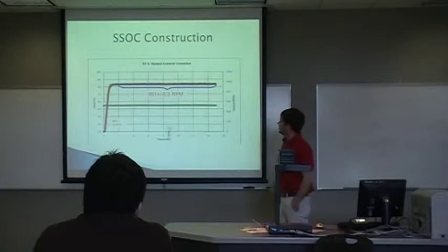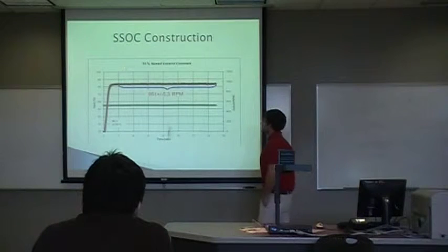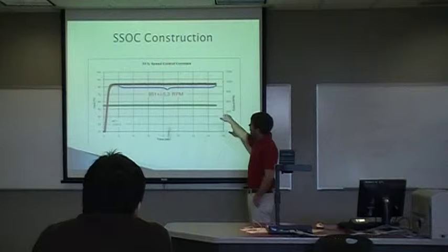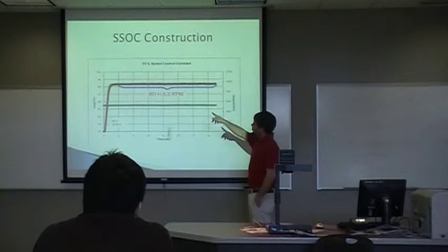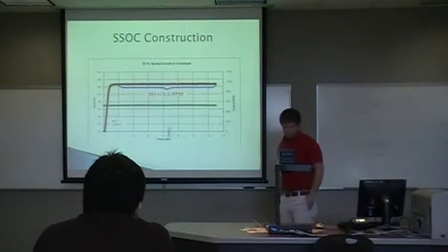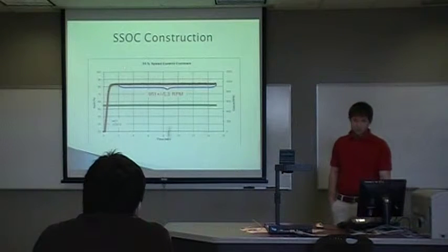As you can see, the constant input for this graph is 55%, and the output, which is the maroon line there, we took the average under the steady state of the output, and that was 951 plus or minus 5.3 RPMs at 2 times standard deviation. We ignored the left portion of the graph because it's considered transient startup, and we're concerned with steady state operation.